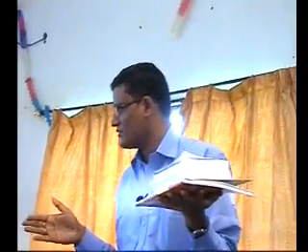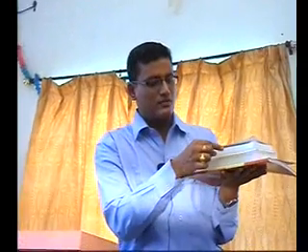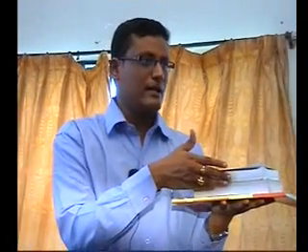When we have different layers, these inherent layers actually contribute to a kind of capacitance. So you will find the capacitances. For example, oxide layer is there, semiconductor is there. Between oxide and semiconductor, we have an interface. This is called the interface region. This interface region will give you a capacitance called interface capacitance, CIT. Oxide semiconductor interface capacitance, and we have junction capacitance. Various capacitances are there in MOSFET.